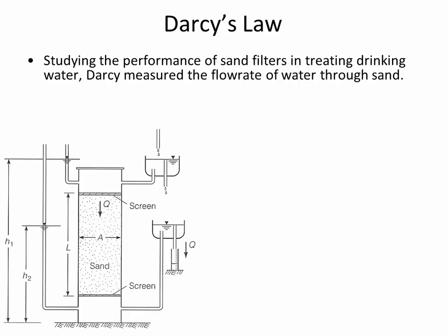All right, Darcy's law you probably remember from soil mechanics, and it's a way of classifying the hydraulic conductivity of soil. We've talked about how clay is bound to water more tightly because of its negative charge on the soil surface. And sand, on the other hand, allows for water to pass through it more easily. Darcy's law is a way of testing that to find out what is the hydraulic conductivity of soil.